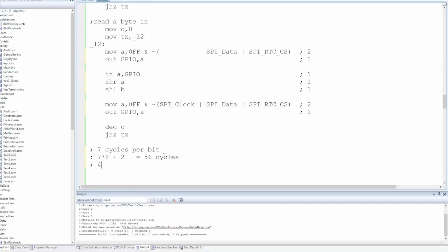So we've got 4 megahertz. So that's about 71k a second. That's pretty fast. We've only got 64k of RAM, so the biggest single program we could load off a storage device over SPI with the software bit banging would take us just under a second to load. That's pretty good. But is it fast enough? Okay, 71k a second. That's actually pretty good. If we were loading programs, that's the largest program we could ever fit in memory, is going to take less than a second. So I'd be kind of happy with that.